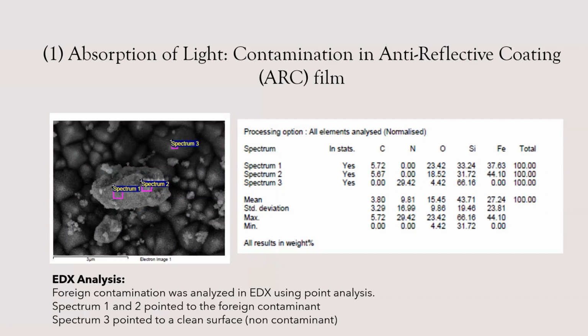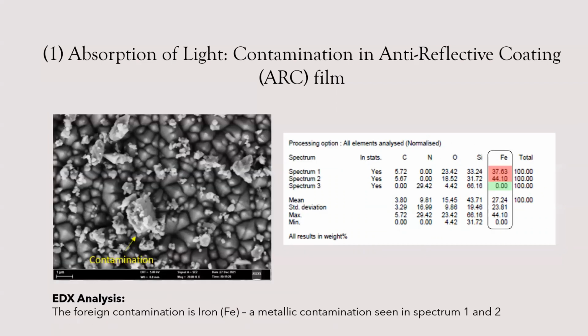With the EDX analysis, the contamination is determined to have the presence of a metallic element, which is iron. Determining what particular contamination is present on the defect will help the engineer to find the source and correct the problem.